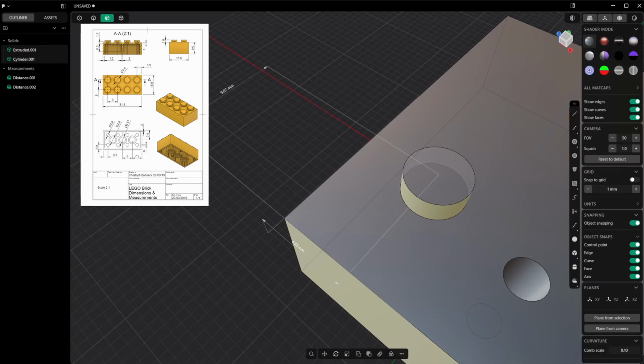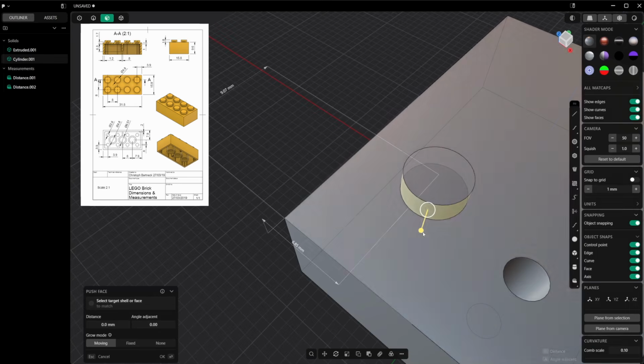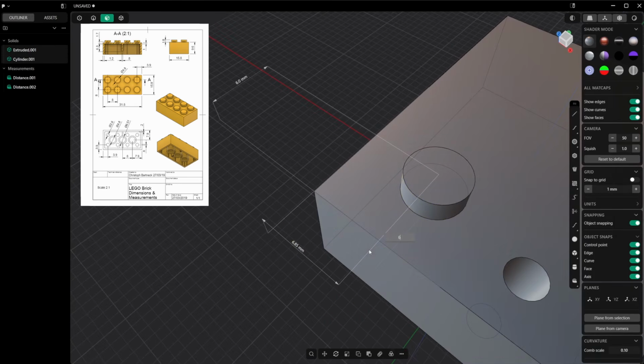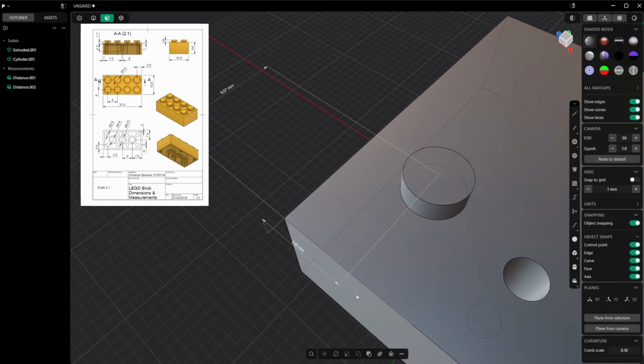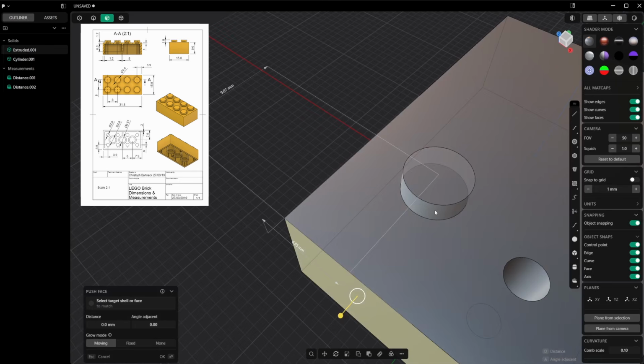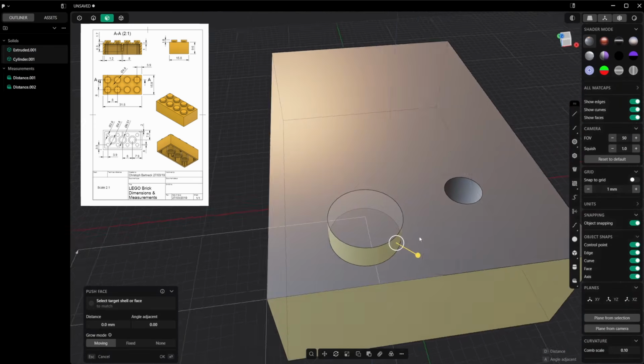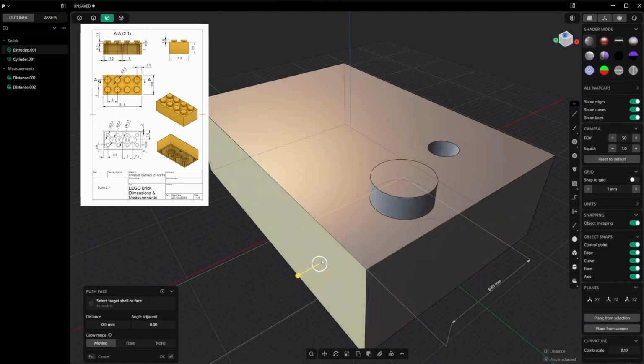Actually, wait a second, Nemo from the future here, because I noticed something really interesting that I didn't know before because it was not working for me. So if I select this side of the cylinder and then the face, and I push equal, if I set a specific size here, you can see the side is moving. However, if I first select this face and then I select the side of the cylinder and I push equal, I can actually move it around real easy.